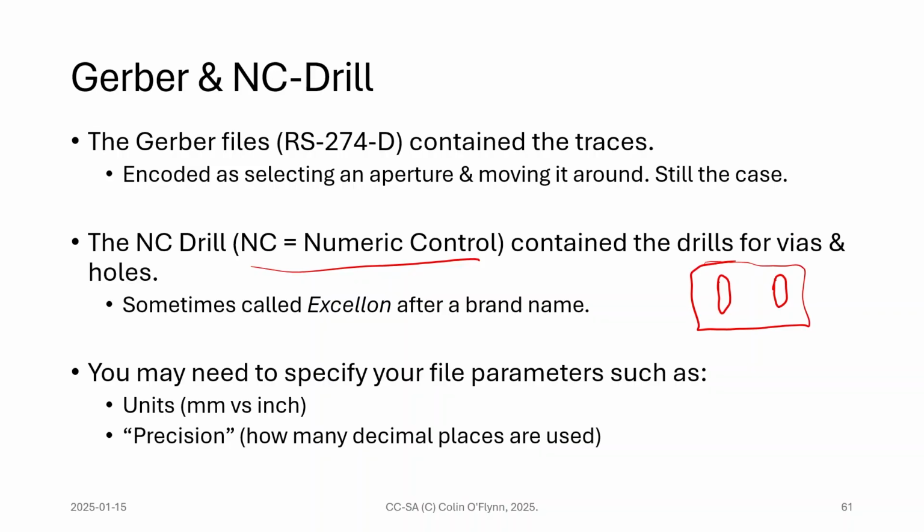You also may have files for holes that are not plated through. If you remember when we talked about it, most of the time we drill a hole and then plate it through. But you may have holes that you don't want plated through, for example if you're mounting things in them and don't have electrical pads on the top and bottom. You could end up with separate holes that are not plated through holes. Those get separated so that the manufacturer knows what's supposed to be plated through and what's not.